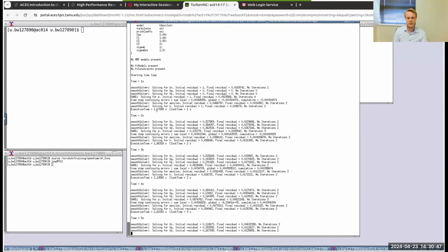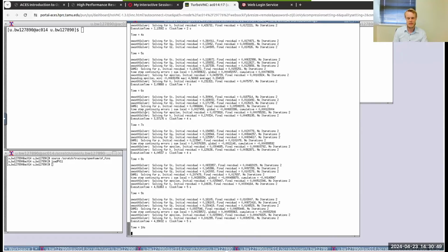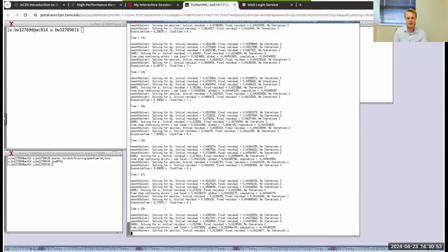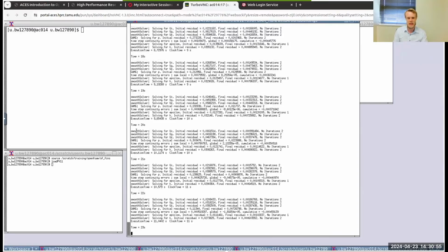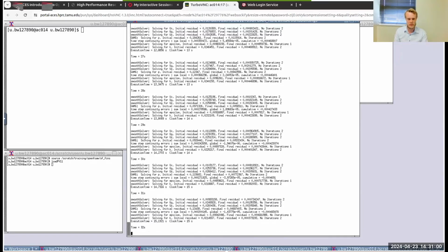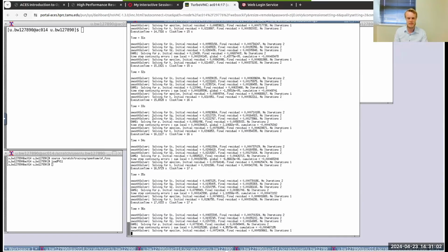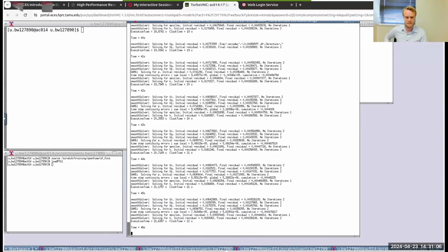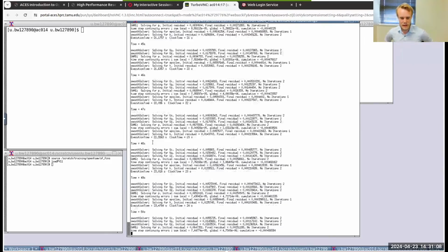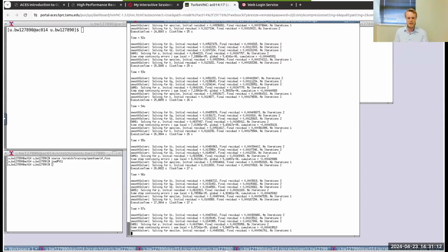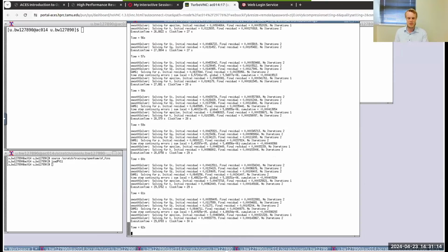If you remember before, we picked the smoothSolver matrix solver for velocity, and we picked the GAMG matrix solver for pressure. You can see in every time step that it's telling you it's using those solvers that we picked. And this is gonna run now. I set the end time to 400 seconds in the controlDict.